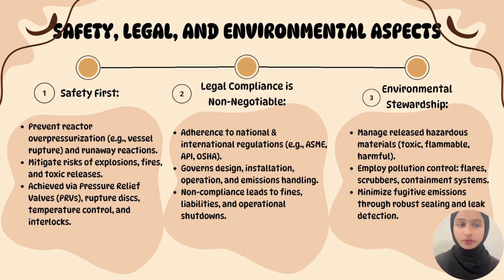If this gets out of control, things can go very wrong, like an explosion, fire, or toxic gas leak. Our safety systems, such as pressure relief valves, act as our frontline defense. They automatically release excess pressure to prevent these dangerous situations. We also control temperature very carefully, as a sudden rise can cause rapid pressure increases. So our system has emergency shutdowns to keep everyone and everything safe.